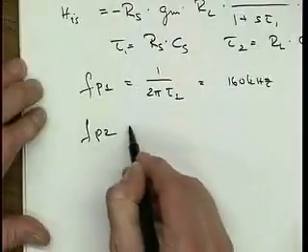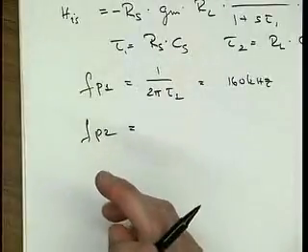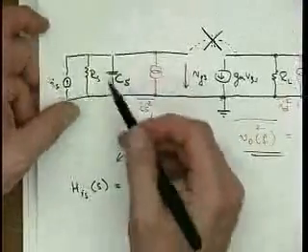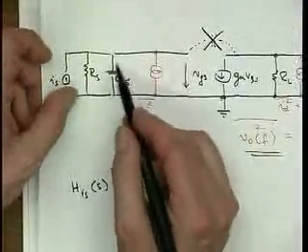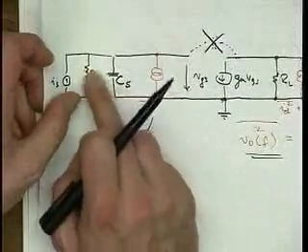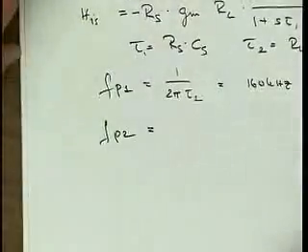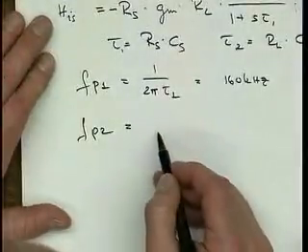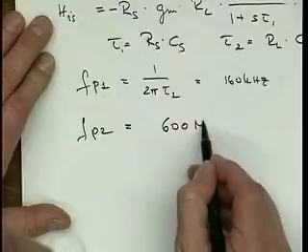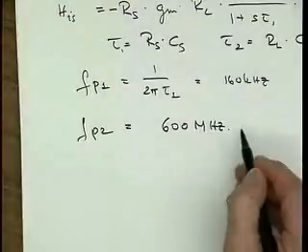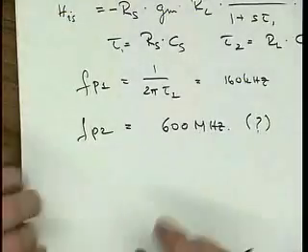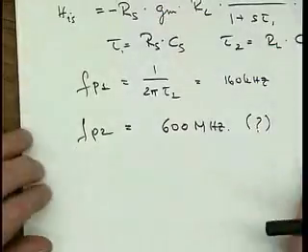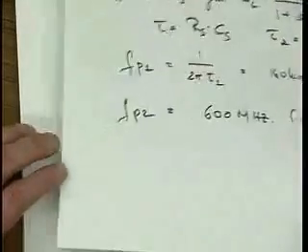And then FP2, by the way, is often the problem in how do we build a fast fiber optic receiver? Well, for good sensitivity, you want a big diode so that produces a large capacitance, and then the impedance here is fairly high also for a good diode, right? So this is about 600 megahertz. Probably a little bit questionable whether we should even consider this anymore. I do it here because you will then see a more interesting plot we can try to interpret.